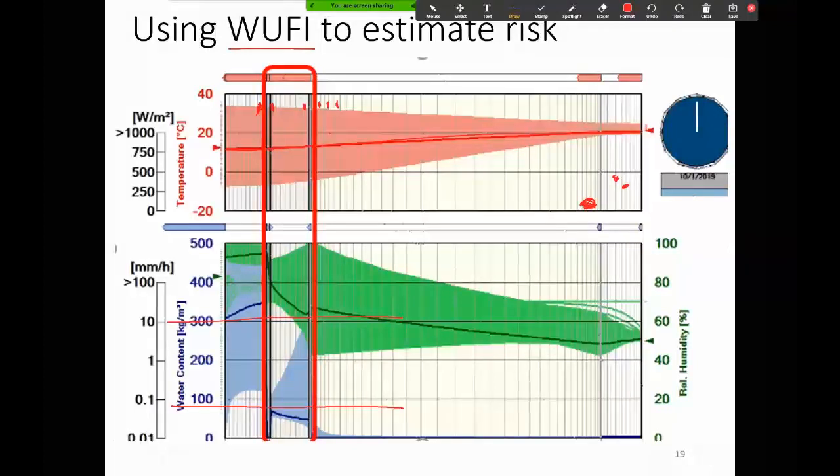So here's my line across that same envelope, and you've got your relative humidity. This is the history of where your relative humidity has been, but this green line here is telling you where your relative humidity is at any given point in your wall assembly. So you can say, up here my relative humidity is really high, but that's inside of my building. Here, my relative humidity is just over 60. I might be okay there depending on the temperature outside. And then here, it's dropping down.